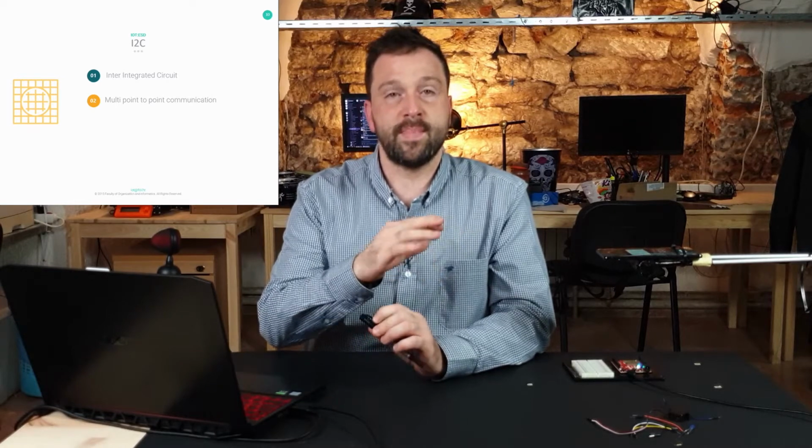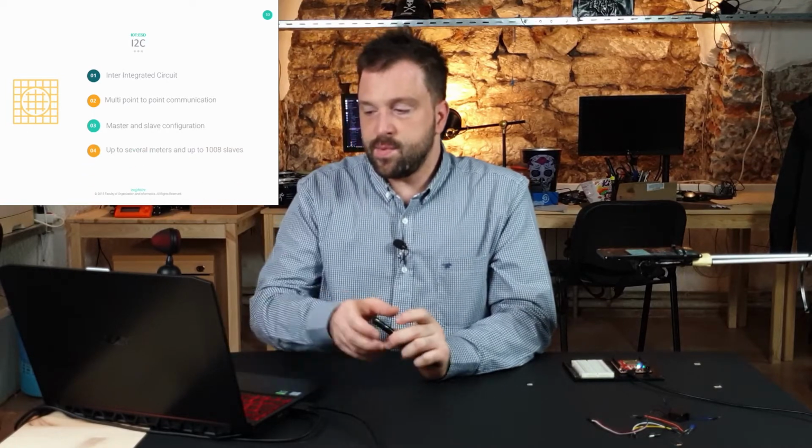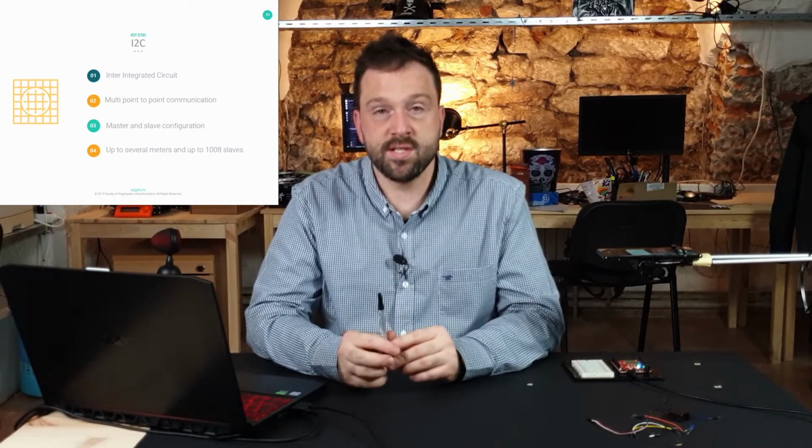Hi guys, today I'm gonna talk about one of the most famous protocols in embedded software development. It's called I2C. It stands for Inter-Integrated Circuit, and this protocol allows multi-point-to-point communication between different elements or devices on the embedded solution. And it is a master and slave configuration, and it will allow distances of communication of up to several meters